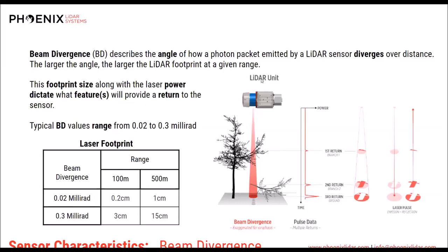Thinking about a general UAV project, say 50 to 100 acres, I would love to see at least 20 ground control points. While if this 50 acres was in Saskatchewan, in snowy territory with no hard surfaces anywhere to collect ground control points, I could see why you would not collect up to 20. And while these ground control points are very important to assess geospatial accuracy, absolute accuracy, they're not actually going to increase the range accuracy of your LiDAR sensor.